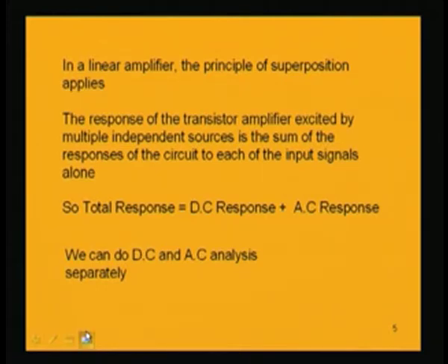signals alone. So, if we have a DC voltage for biasing, if we recall, earlier we were discussing the DC analysis, because we were concerned about the DC equivalent circuit, since we were concerned about the biasing schemes and the operating point. That is why, when we considered the DC equivalent circuit, we were only discussing the DC condition. Now, when we apply an AC signal for amplification, we will be concerned about the signal analysis, that is, the response of the BJT for an AC signal.